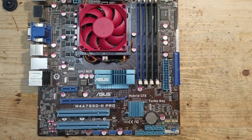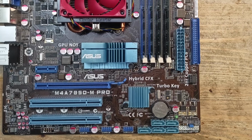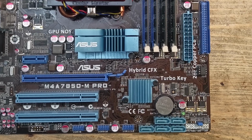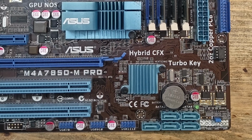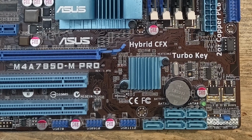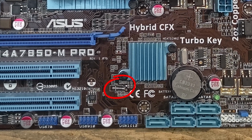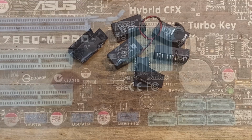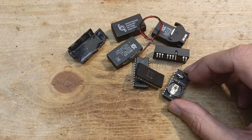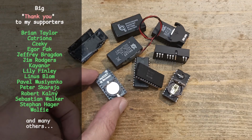On more modern mainboards starting around Pentium times, even some later 486 mainboards, from there on until today the RTC circuit is integrated into the chipset. There are no dedicated components for that anymore, except the crystal oscillator. That 32 kHz guy can still be found on most, if not every mainboard today. But on this channel we are mostly interested in the older stuff. That's why I'm happy to have more options for the repairs.